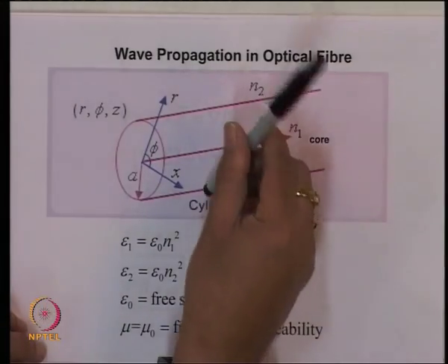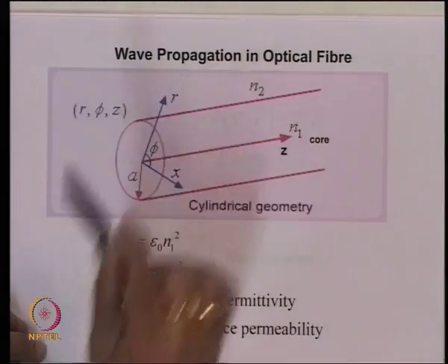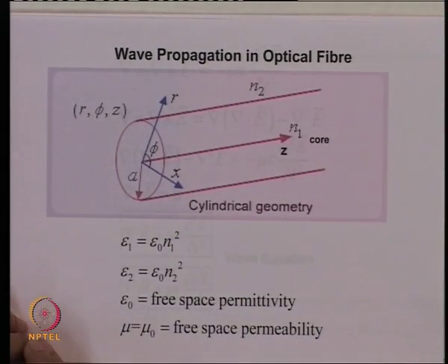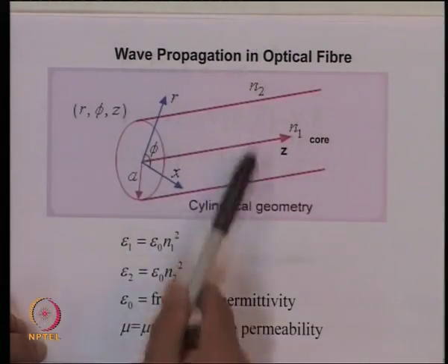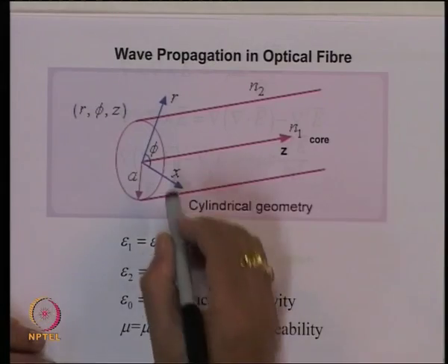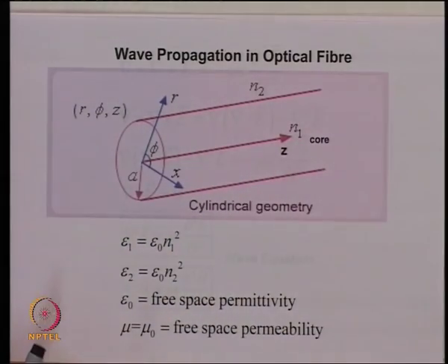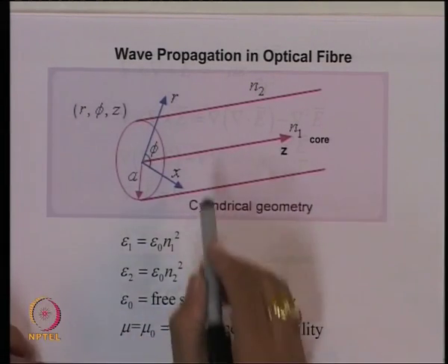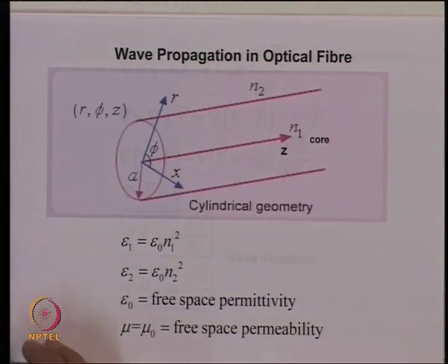Any direction which is perpendicular to this, which we call the transverse direction, there is nothing special about it in this cross sectional plane, but this direction is a special direction. So, what normally we do, we take the two field components which are in the direction of propagation as the independent components and try to express the remaining four components in terms of these components.